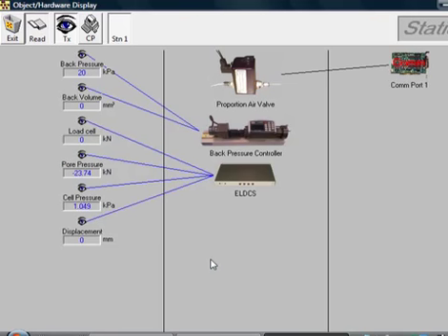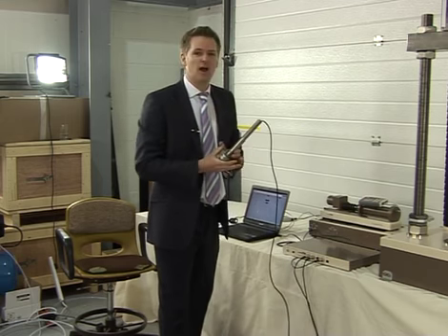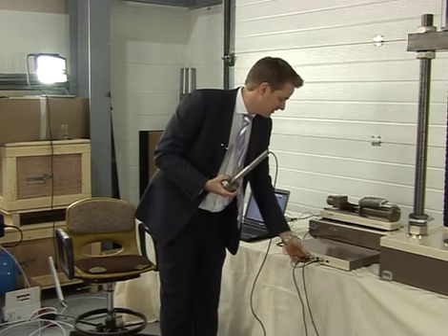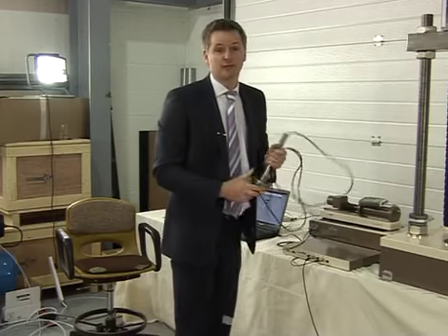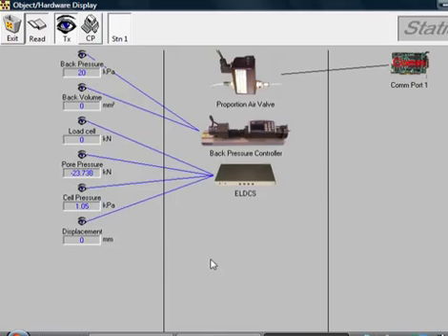I can see that without too much effort I can push 0.3 of a kilonewton, so maybe 30 kilograms. So that tells me that that's reading about right. At this stage that's good enough for me to know that the transducer's essentially reading the right thing. What we're looking for there is that I don't manage to push 300 kilonewtons or 3 kilograms, something like this, so that we know we're in the right ballpark.